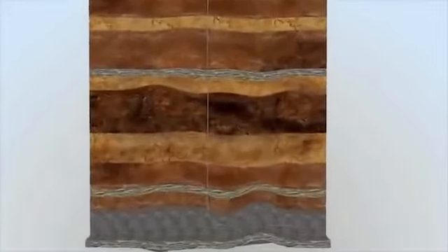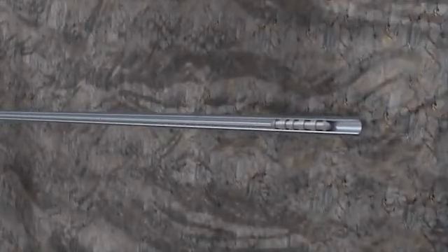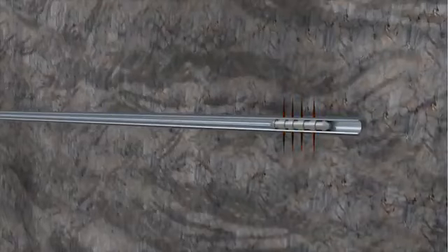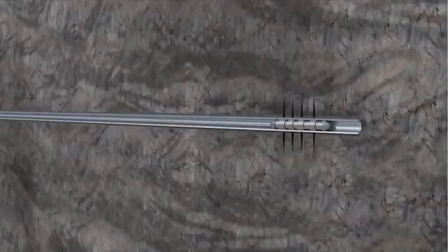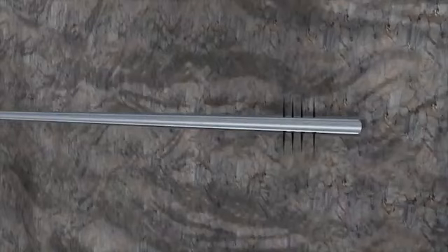The first step in completing a well is the creation of a connection between the final casing and the reservoir rock. This consists of lowering a specialized tool called a perforating gun, which is equipped with shaped explosive charges, down to the rock layer containing oil or natural gas. This perforating gun is then fired, which creates holes through the casing, cement, and into the target rock. These perforating holes connect the reservoir and the wellbore. Since these perforations are only a few inches long and are performed more than a mile underground, the entire process is imperceptible on the surface. The perforating gun is then removed in preparation for the next step, hydraulic fracturing.